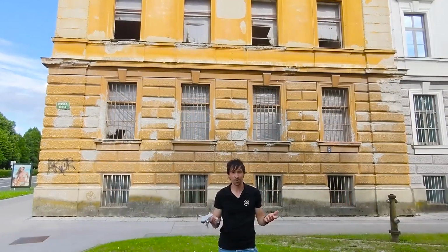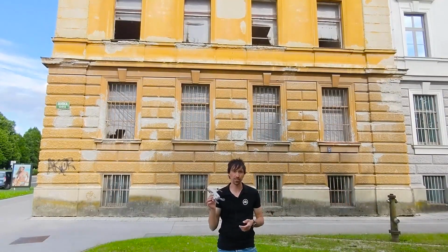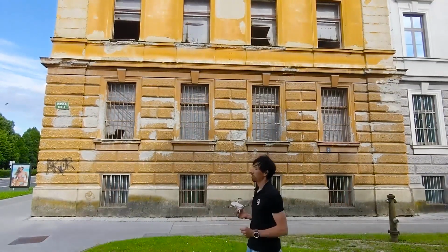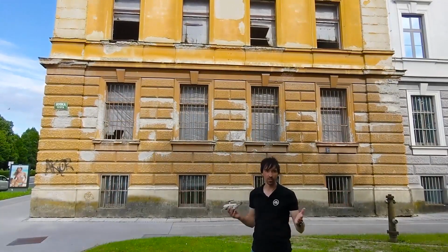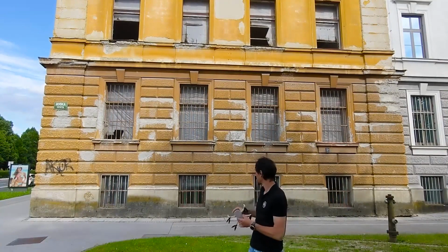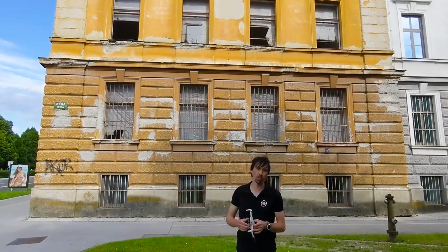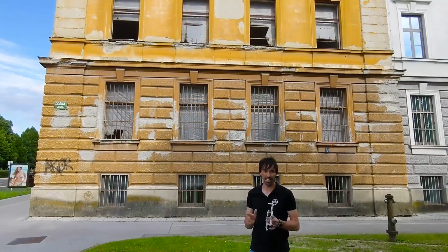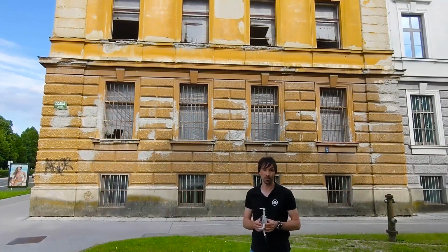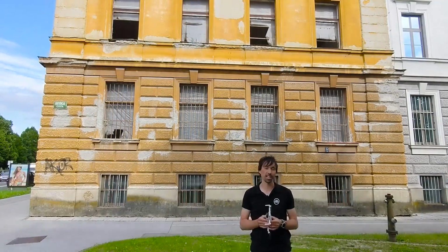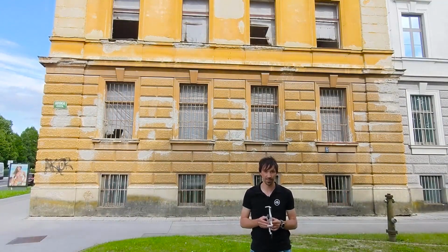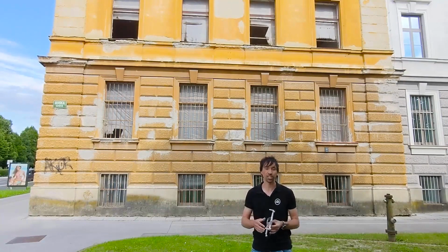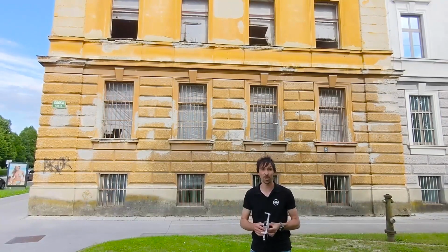Okay, I finished with my field work. It was a 1 battery flight, I think approximately 60 images for this building facade, and I used the measuring tape to measure 2 distances between windows, which will help me to orient the model and get accurate dimensions between specific objects we need to deliver to our end customer. Let's get back into the office, import the images, and create a stunning 3D model.